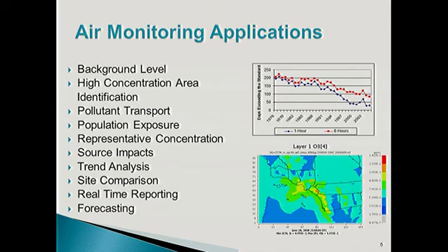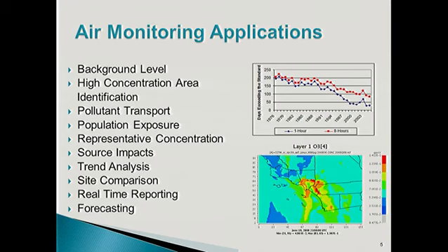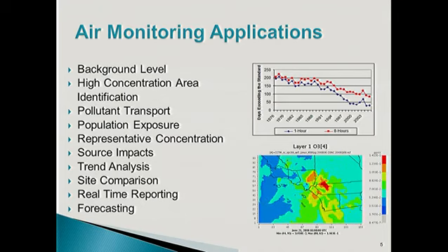Some of it comes from the main network, such as background level data. It's to understand, without major sources nearby, what the air would look like. In certain areas, the background levels could actually be higher than other parts of the nation. It also gives you a good baseline value to compare your air quality against. For example, at South Coast, we've predicted the ozone background level to be about 40 ppb. If we're only given 70 ppb to meet the national standards, that only gives us a small cushion of our ozone inventory that we have to play with in order to meet the attainment goals.